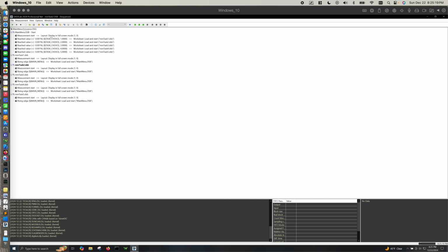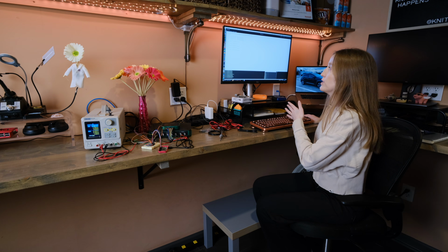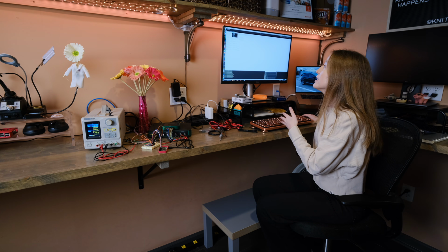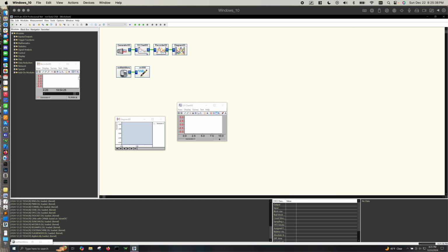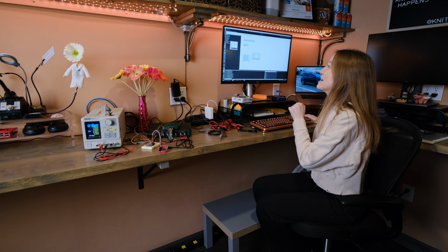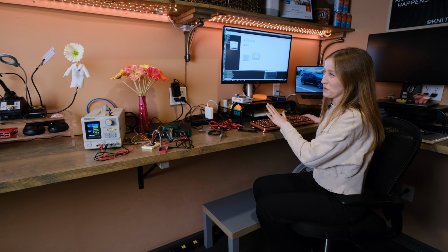One thing I have found is make sure you hit the stop button from the sequence window if you're wanting to stop the overall sequence. Because like I said, the sequence file and the worksheet file are 2 separate things. I've found that if I have a sequence running, but I'm in the worksheet view or layout view of the worksheets and I try to hit stop there, it seems to cause some chaos and DASYLab isn't sure what I actually want it to do.